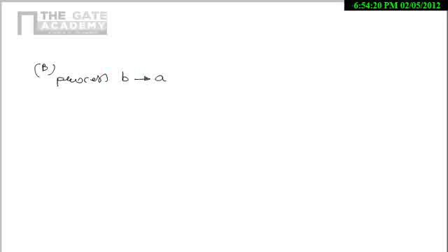Now let's come to part B. So in part B, it is given when the system is returned from B to A. So process is from B to A. So final is A, initial is B. Along the curved path, the work done on the system is 21 kJ. Work done on the system means negative, minus 21 kJ. We have to find out the heat, that is QBA.